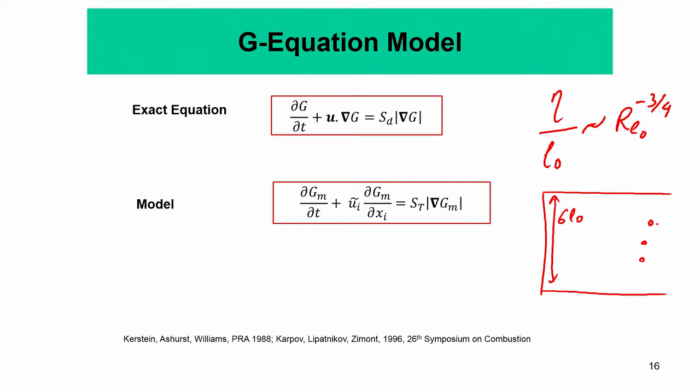That is why we cannot solve what happens inside the engine just by solving all the continuity, momentum, temperature, species equations as well as the constitutive relations as is, and that is why we need to seek models which describe their mean propagation, mean properties or their filtered properties, as is done in LES, large eddy simulation. Okay. So, that is the thing.